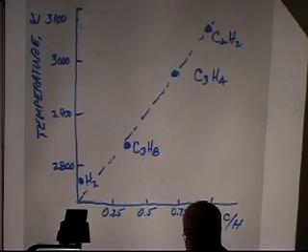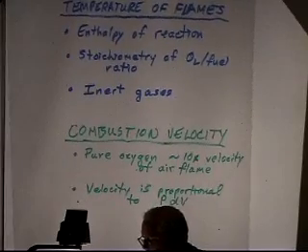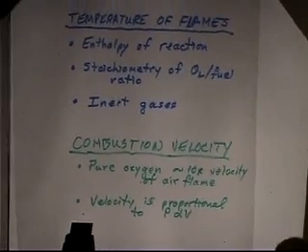It's basically the enthalpy of burning carbon and the enthalpy of burning hydrogen. Hydrocarbons actually are a mixture of the two. And so that tells me the heating value of the gas or the enthalpy of the reaction. In addition, I have to worry about the stoichiometry of the oxygen-fuel ratio.